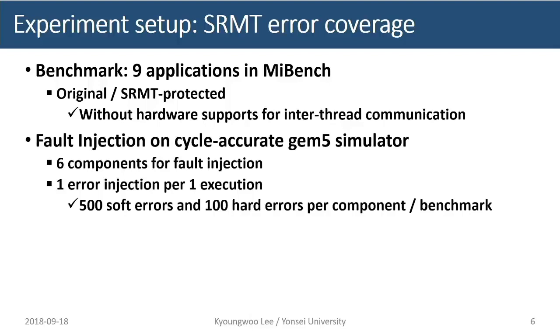On the gem5 simulator, we injected faults at 6 main components, one error per execution. We injected 500 soft errors and 100 hard errors per component and per benchmark.